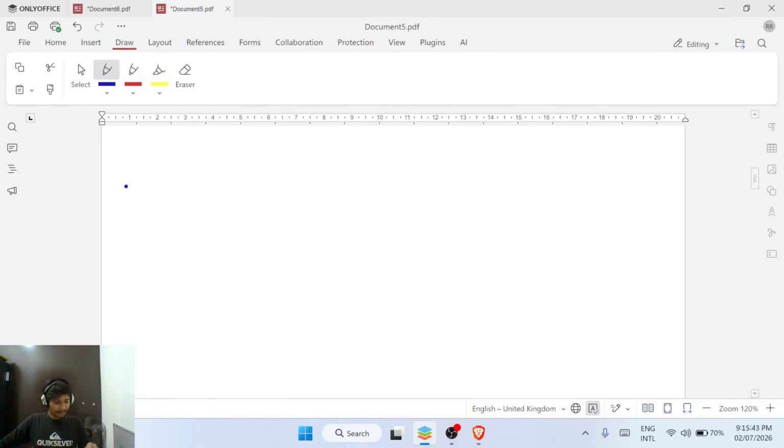We studied that the steady flow energy equation is U1 plus P1 V1 plus C1 square by 2 plus Q is equal to U2 plus P2 V2 plus C2 square by 2 plus W. Please write it anywhere. Now, to find W, we move all the other things to the right side and get the W to the left side. It's very simple, no?